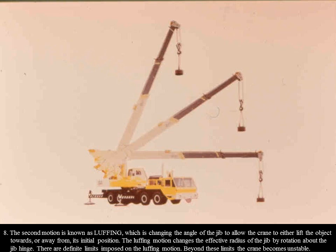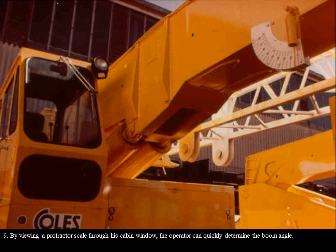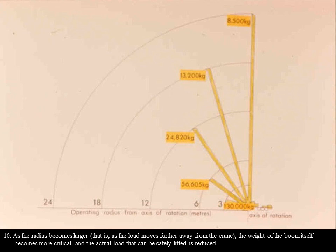The luffing motion changes the effective radius of the jib by rotation about the jib hinge. There are definite limits imposed on the luffing motion. Beyond these limits, the crane becomes unstable. By viewing a protractor scale through his cabin window, the operator can quickly determine the boom angle.